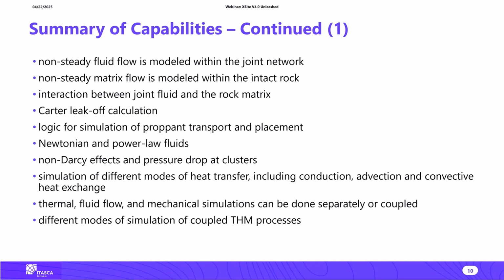But then, for the sake of computational efficiency, we can carry out coupled processes more efficiently, where some of the processes are advanced in time much faster, based on the assumption that, let's say, the mechanical model is in some kind of quasi-static, quasi-equilibrium state, or the fluid flow model is in a steady state.